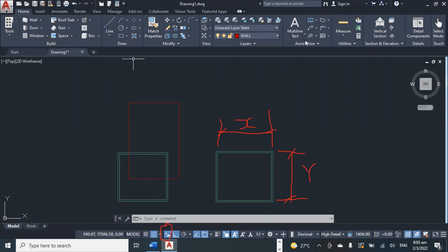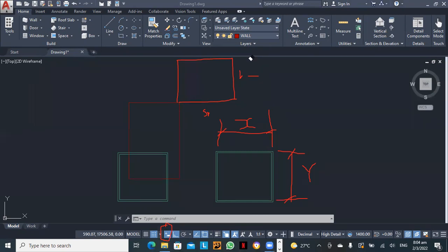So typically for the standard AutoCAD, in that case, what you would do, so it should have been here. In that case, we start here. The 5,000 should have been here. And the 6,000 should have been on this side, 6,000 here. But in this case, we end up with something like this. To solve that problem, please note that once you're using AutoCAD Architecture, you must enter the @ sign. That's a big difference, the @ sign.